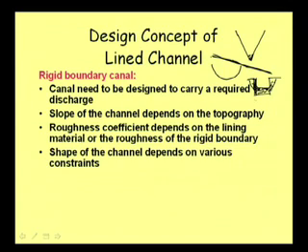Rather than that, if we give an inclined shape, it is otherwise also stable. So, lining is not required to support the soil against collapse. Erosion resistance is what we require it for, but to prevent slope failure the thickness of the side lining is not required, so the thickness will be less, and that way it may be preferred. So, depending on various constraints, we need to decide the shape of the channel.